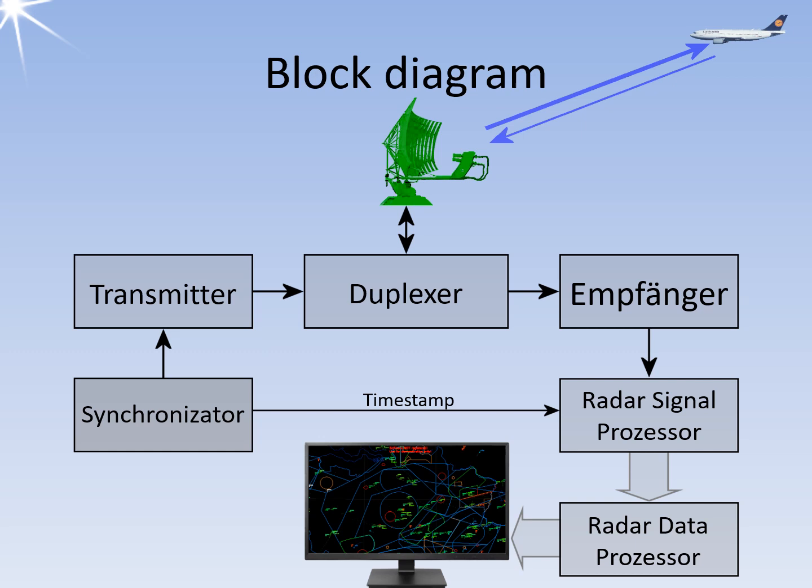With the radar data processors, these delay times are no longer constant. Here delays of several complete antenna rotations can accumulate. For this reason, a timestamp must be supplied with the dataset during digitization to be able to evaluate the timeliness of the data. The echo signal is digitized as early as possible, usually already at the intermediate frequency level, but sometimes also directly as a high-frequency signal.